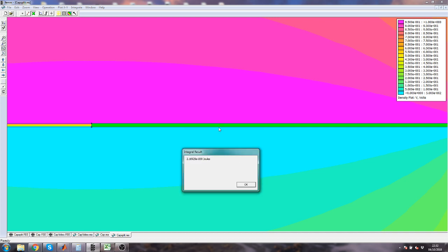The energy is not stored in this region. The energy is stored as electric potential. And there is an electric flux in this region, which is the expression of that stored energy. Really, it's because there is charge on the plates, and the charges are attracted to each other, and that maintains the charge there. And the charge is held across a voltage, and that voltage represents the potential for the work to be done. The charge must flow to do the work. So the energy is not stored in the FR4. I did say that, and it's not quite right.